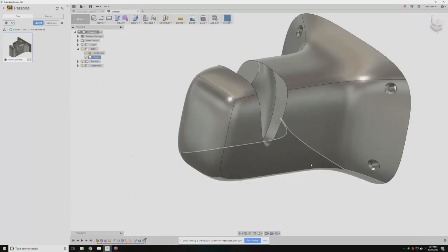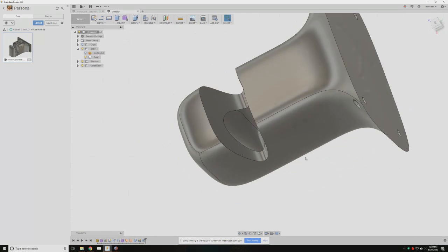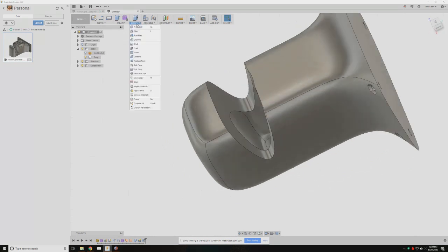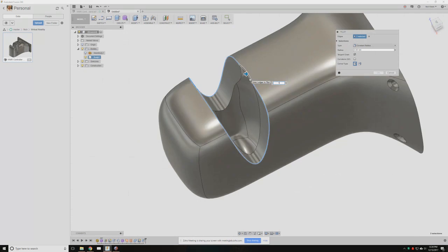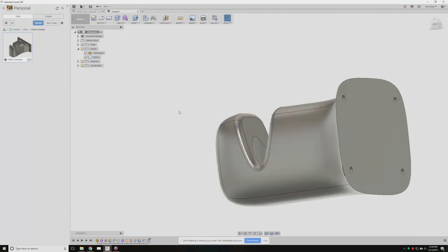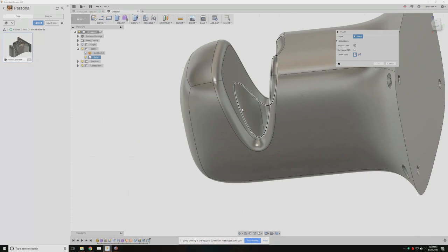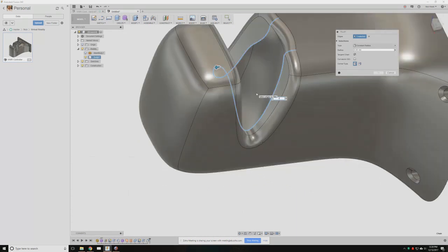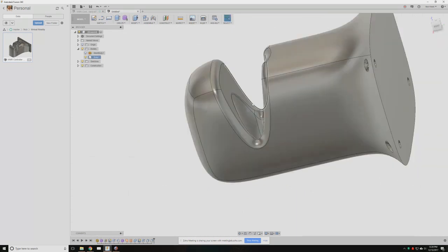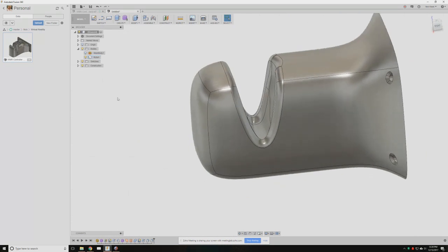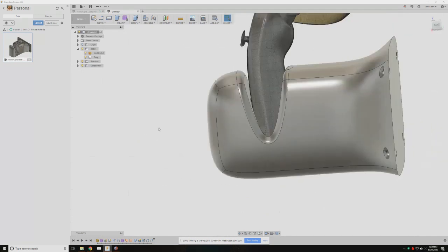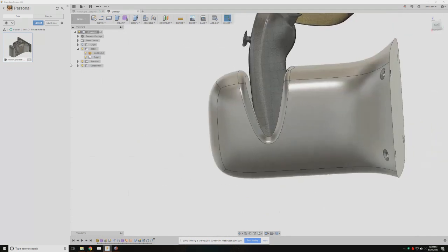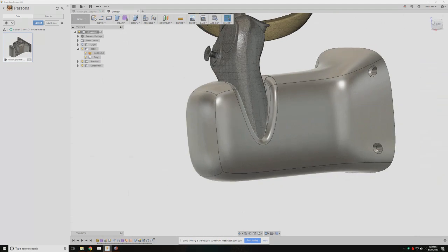So now that's kind of an interesting shape. I think I didn't do that entirely correctly, but now I should be able to more easily fillet, so that's a 5 millimeter fillet there. And then I can maybe fillet the inside as well, maybe also at 5. Yeah, and that saves a little bit on the printing time. And if I bring in the mesh body again, that's what it would look like when it goes in. It would still kind of cup it in there a little bit. The one that I did before is a lot better, but it gives you a good idea.